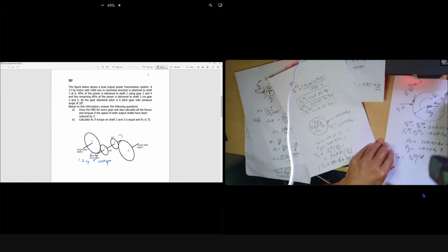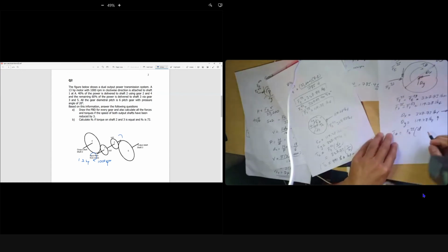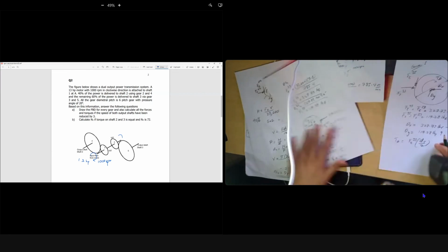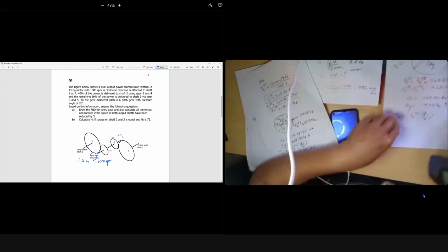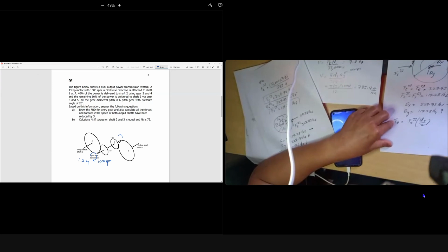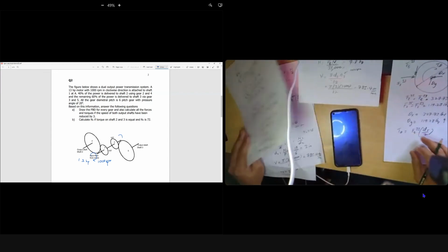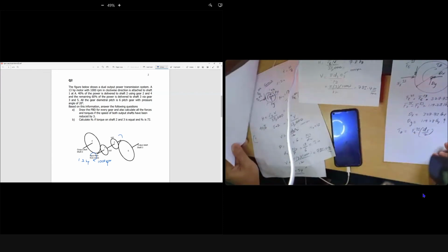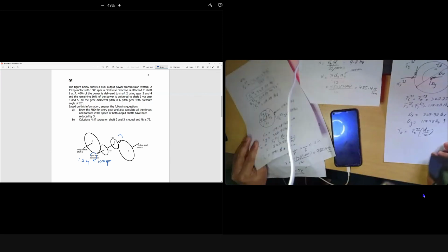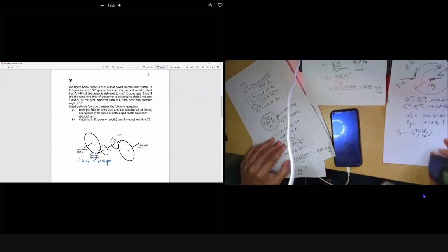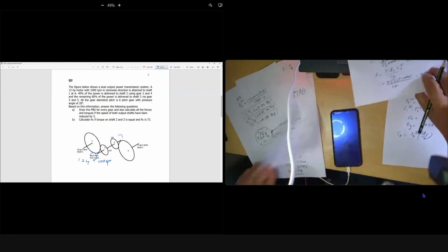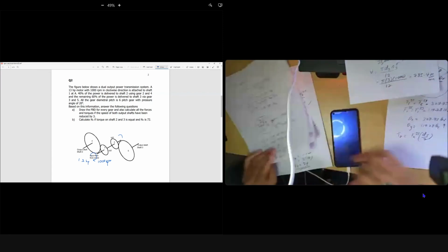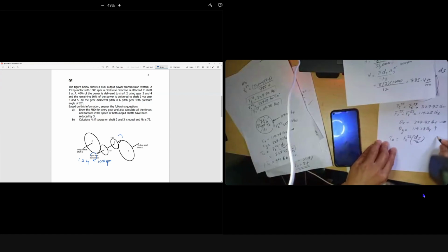5, you can forget diameter 5. Okay, diameter 5 over 2. Remember the speed ratio from earlier, the same as for gear 4 that we saw. It means 4 and 5 have the same value, so the diameter of 4 and 5 is the same, because it is reduced by 3. Your diameter 5 is the same as what was our diameter 4, which is 54.